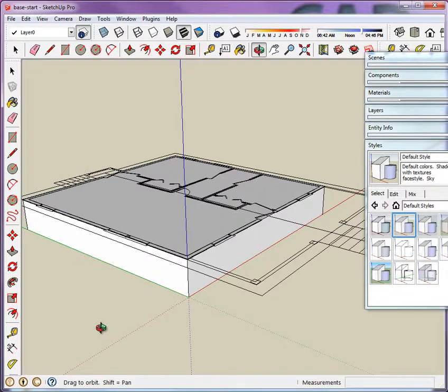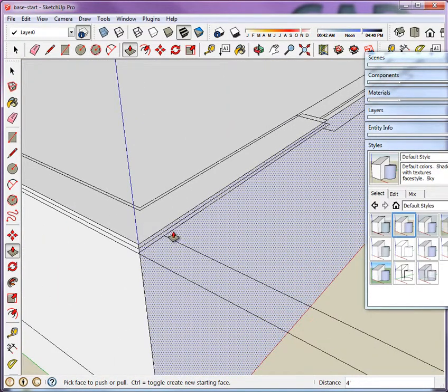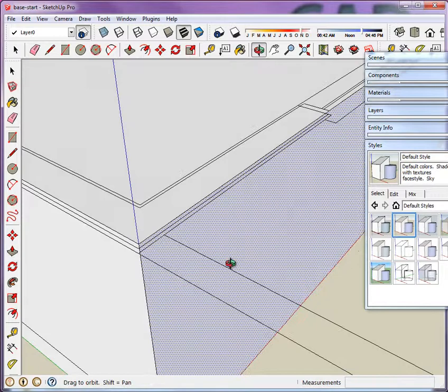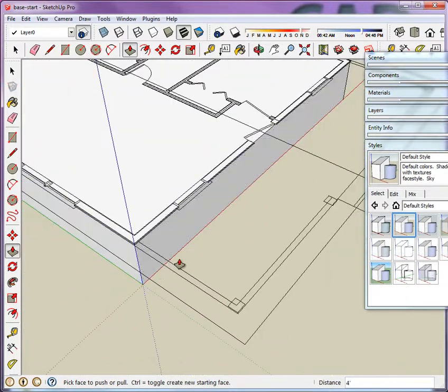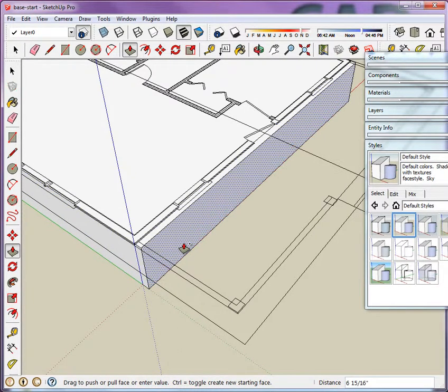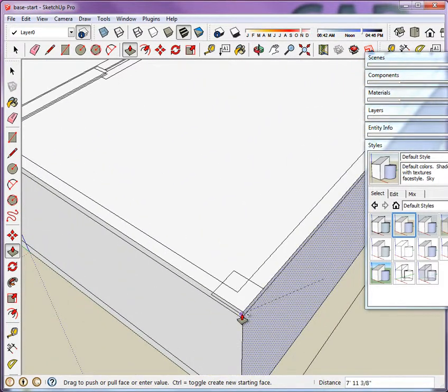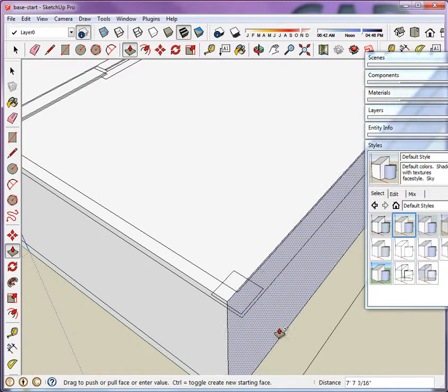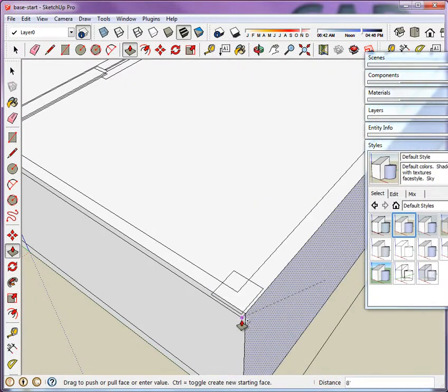And that would actually include what would be the rough floor at the top portion of it. Now you'll notice over here that we've got the porch that extends a little bit further out, that actually aligns with the finish, right? So here's another way that we could use push-pull. This time, if I use Control, what I do here is I create a new and separate surface. And for that, I can align that with the end of the porch there. See if I see it clearly. Okay, right here. And you'll notice how I can snap to vertices.